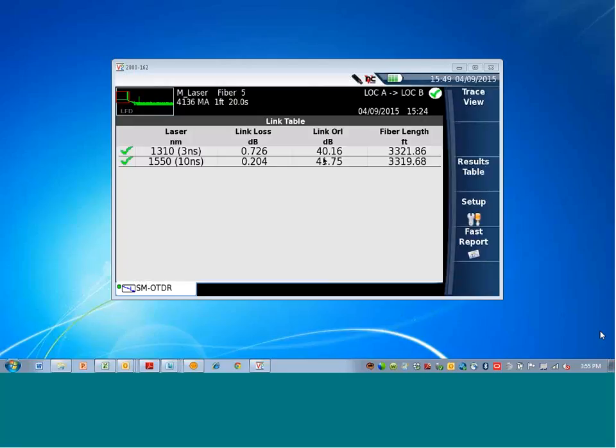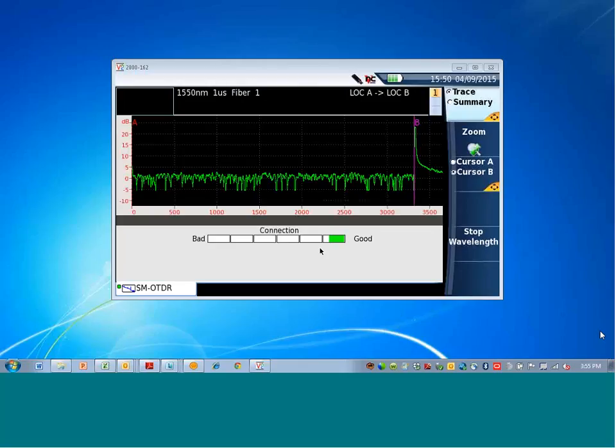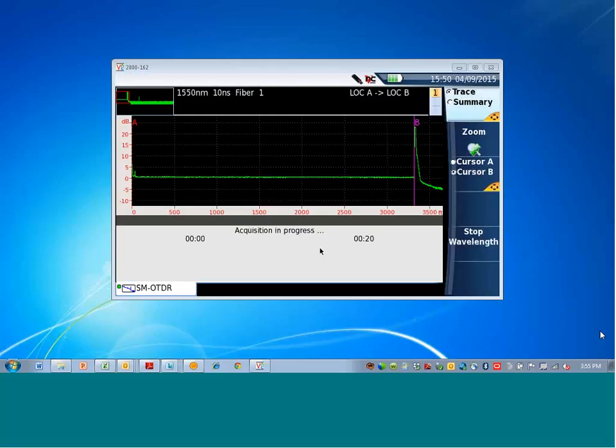and the OTDR will now go into an automatic configuration. Note it says Auto Configuration in Progress. This means the OTDR is picking the correct optical settings. There is a connection check. Good and bad is available. If the OTDR is plugged in clean, the connector is plugged in all the way, there is not a UPC or APC mismatch, the connection will show up as clean.